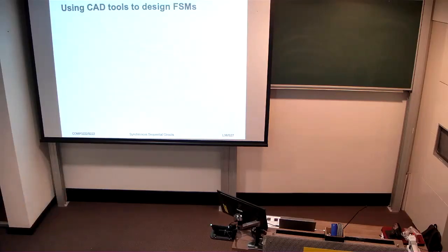Yes? Yes, it is different. We defined it, or we required it to be different, and that's what gave rise to the Mealy design. Namely, what we said was, we want the output to be 1 during the clock period that W is high for a second clock period. So we changed the specification, and that gave rise to a shift forwards in time of the output. It moved forwards by 1 clock period.